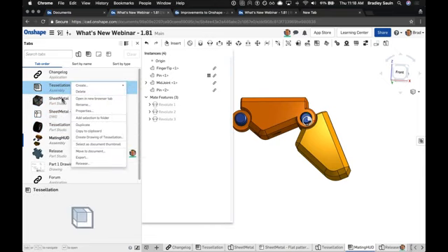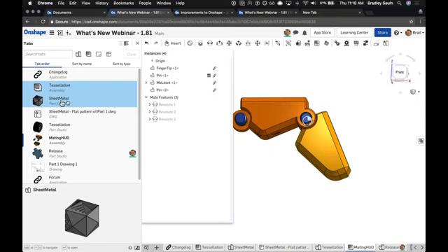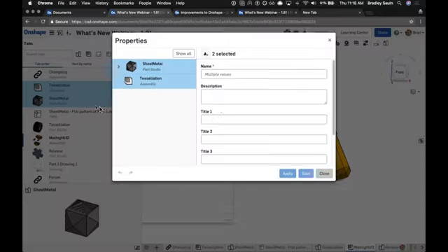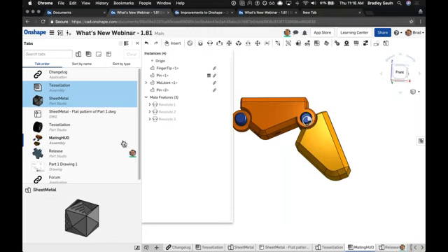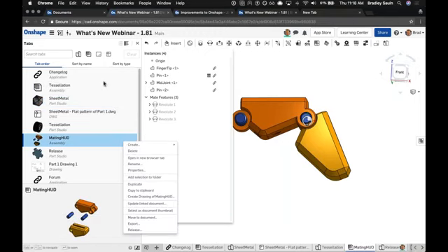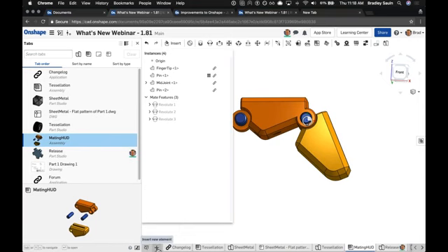So whether I have an assembly and a part studio selected by control clicking, I can now move these to a new document, change the properties of both of these components at once, very quickly be able to get these up and running. Or just right-clicking an empty space in my tab manager will give me our create options that we're used to finding from the plus sign in the bottom left. So again, we're just trying to help reduce mouse travel.